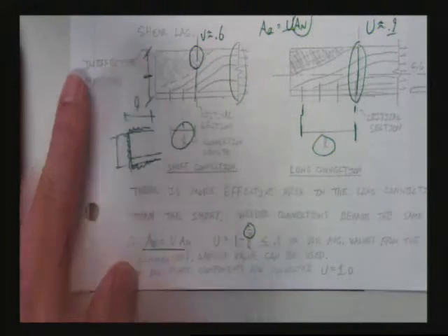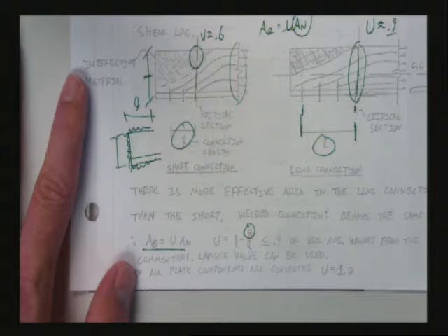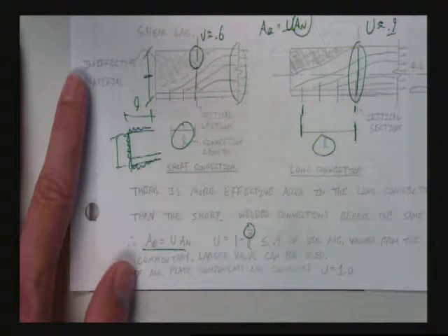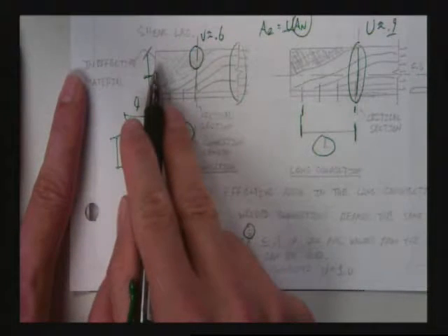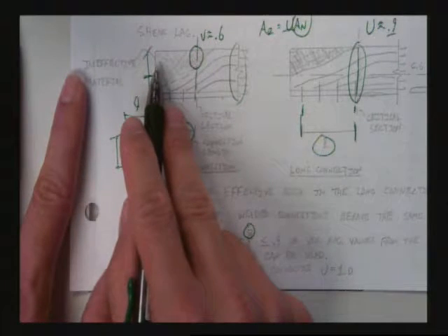What if I just put a bead of weld and there's no steel up there that it's hooked to? Does that help me? That's crazy, all right? But people do crazy stuff when they don't really understand what it's all about. Because you have to have a load path, right? Got to have a load path.